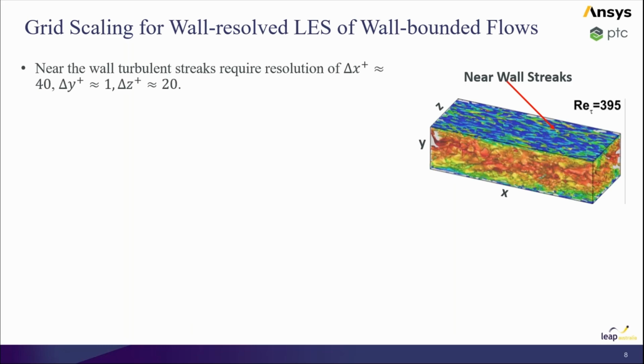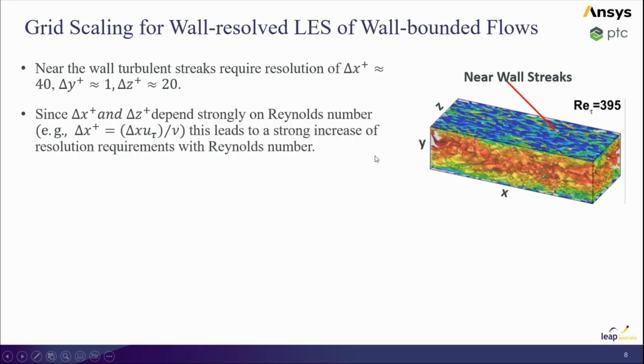So just a little bit of background before I move to the next slide, just to say that because of resolution constraints, things like these channel flows have been examined with direct numerical simulation, and so grid requirements for LES can be rigorously established by comparing with those results, set some guidelines as to how fine the mesh must be. Now, not just normal to the wall, but along the wall and across the wall. We can't do anything in 2D in LES, okay? So we've got to have enough resolution across to build all these structures.